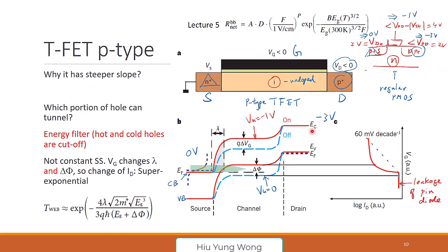Now, someone say impact ionization. Very good. Now, can you tell me why there's impact ionization? At the beginning and the end? What beginning? Can you be more specific? Far left and far right. You mean here? No, at the interface. Here? Yeah. Okay. Can you say why here I have impact ionization? It's a steep band gap. Very good. It's a very steep slope, which means you have a very high electric field, right?